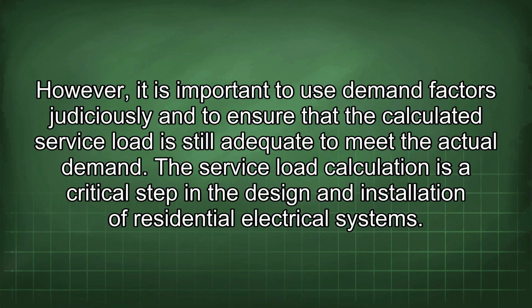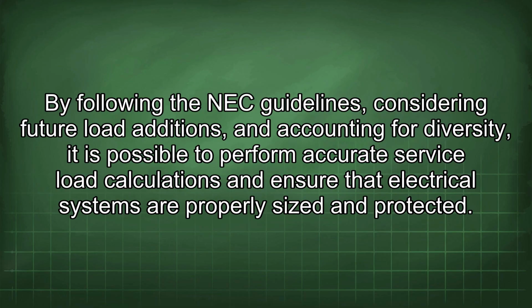However, it is important to use demand factors judiciously and to ensure that the calculated service load is still adequate to meet the actual demand. The service load calculation is a critical step in the design and installation of residential electrical systems. By following the NEC guidelines, considering future load additions, and accounting for diversity, it is possible to perform accurate service load calculations and ensure that electrical systems are properly sized and protected.